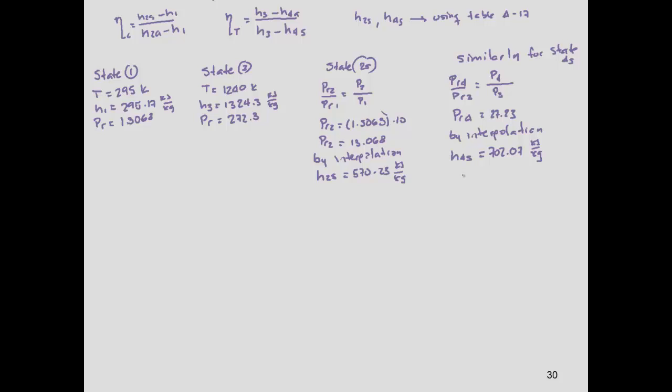So if we substitute, we have that H2 actual is H2s minus H1 divided by compressor efficiency plus enthalpy 1.